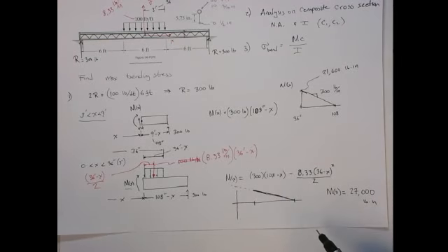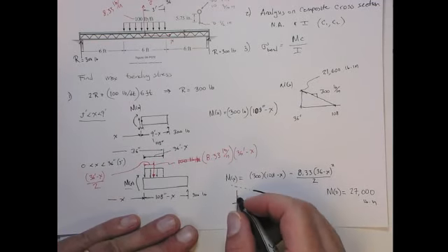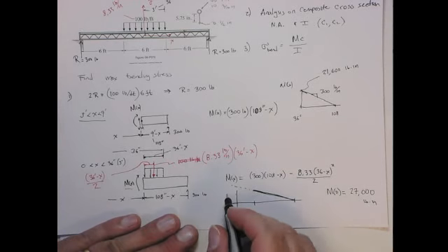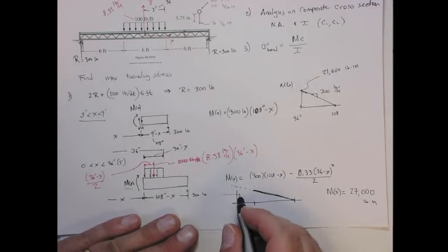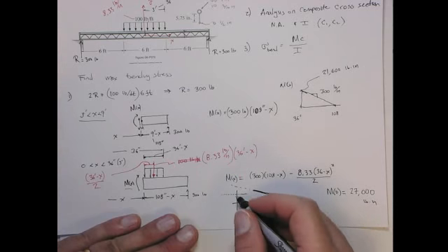So it's still going up. I mean, that seems a bit odd. Let me just double check the numbers. Okay, it's 3420. Yeah, no, that's right. And I also know that because of symmetry, whenever you have these sort of symmetry conditions, the moment has to be at a stationary point. So it has to have the slope of 0 there.